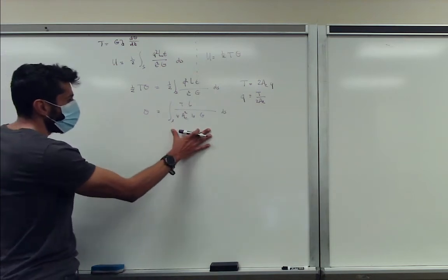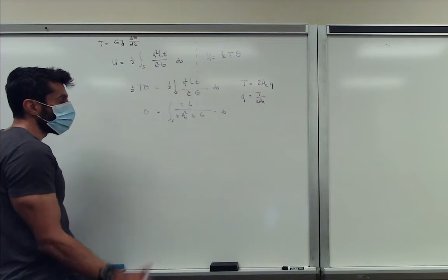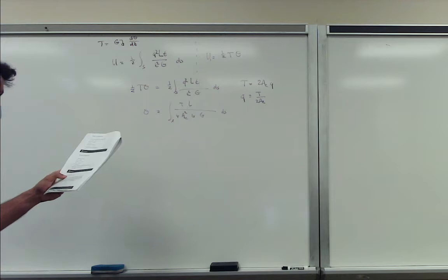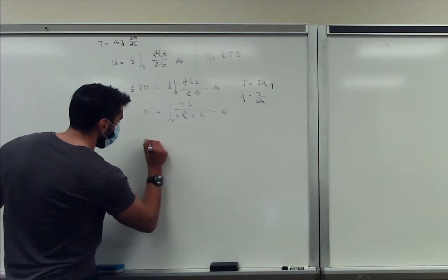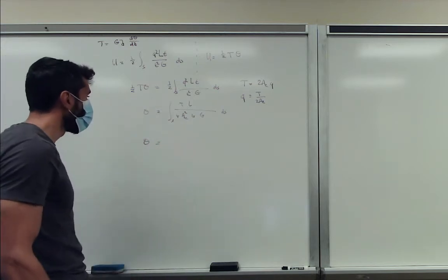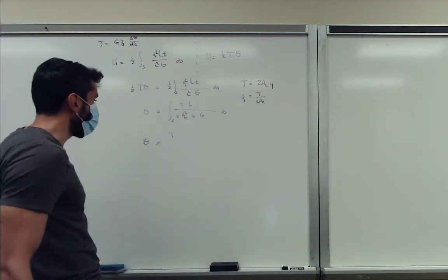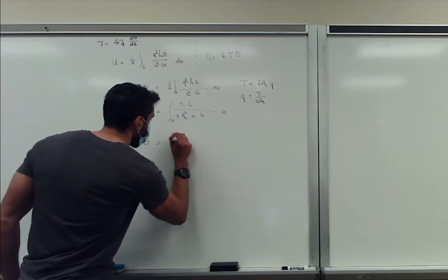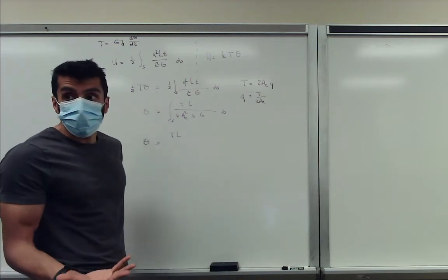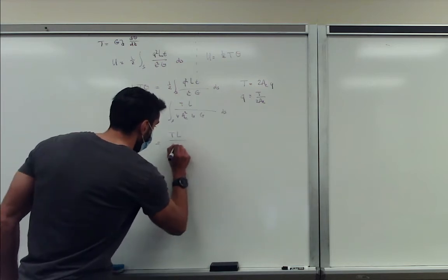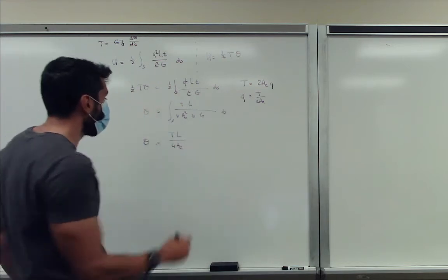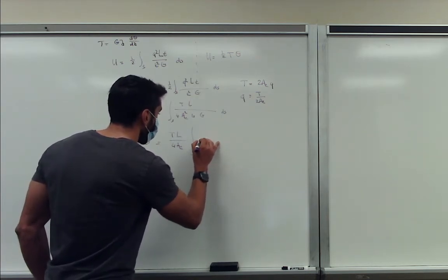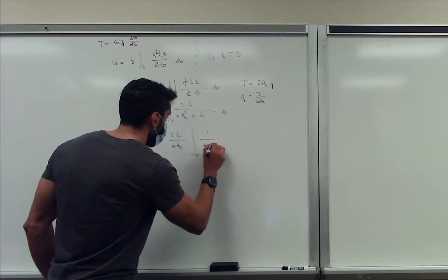So now we can look at this formula. We know a couple of things that are constant that don't vary along the surface, and a couple of things that do vary along the surface. So let's do that. So we know that theta, the twist angle, and the torsion remains constant because it's applied. The length of the beam does not change with the circumference. So that's constant. 4 times the area does not change with the circumference. So that's a constant. And then the things that can change with the surface are the thickness and the shear modulus.